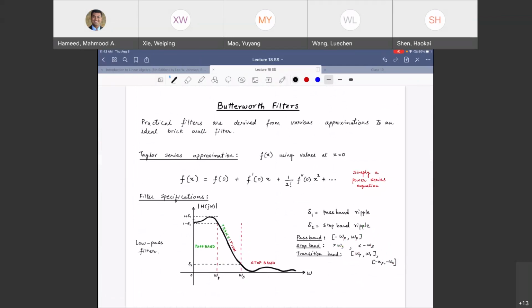The more you keep, right? So what is that going to do? Well, you're going to have to wait forever. So the amount of time that you wait to observe the output of the low pass filter is going to shoot up. The latency is going to increase. So input goes in, the ideal low pass filter output is not coming. It's not coming, right? You're just waiting there. So again, it's a trade-off, the classic trade-off for engineers: performance versus cost.